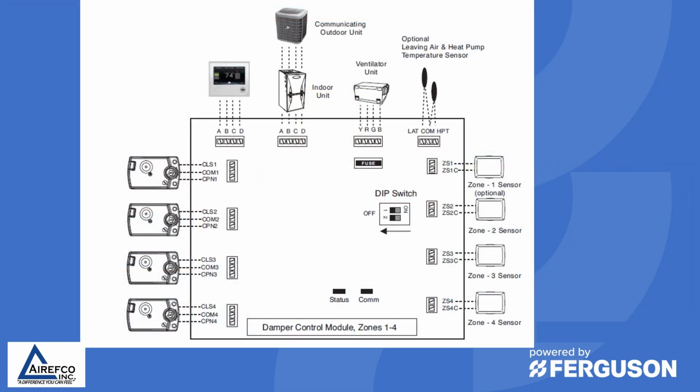Here we see a wiring diagram for the zone damper board, and on the left hand side you see the connections for the damper motors. They are connected by 3 wires, a common wire, a closed, and an open. The damper board sends a signal to the damper motor to open, and it sends a signal to close. On the right hand side we have the zone sensors where they hook in. This is the thermistor only without any control on it. Then you have a connection where you can also attach a ventilator, an HRV or ERV.